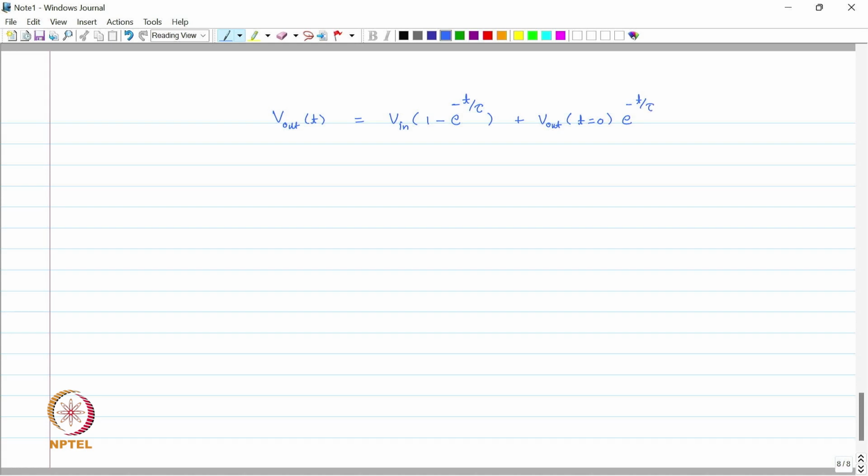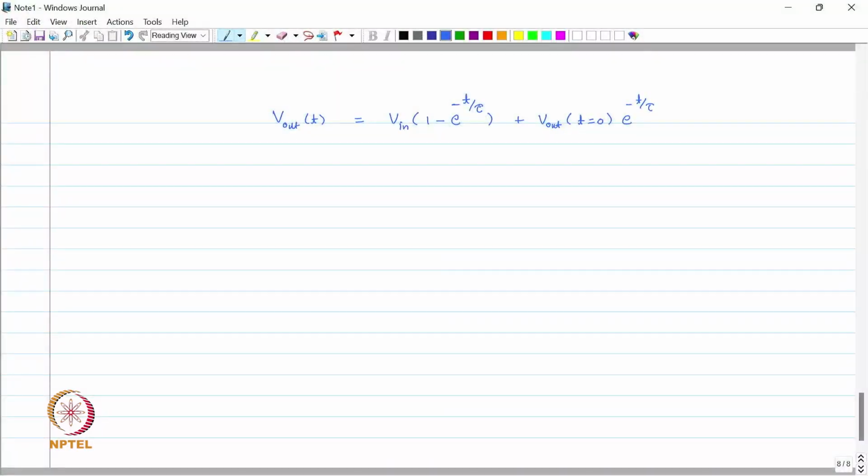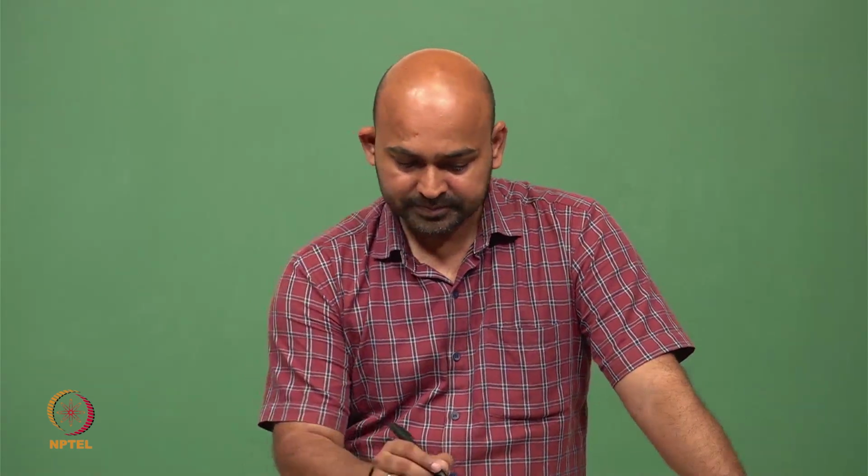So in this equation we can see two things. One is I have replaced RC with a constant tau, because R and C are circuit parameters which we are not going to change. So R and C combined we write as tau, which has a very important function in these equations, and we call it the time constant.